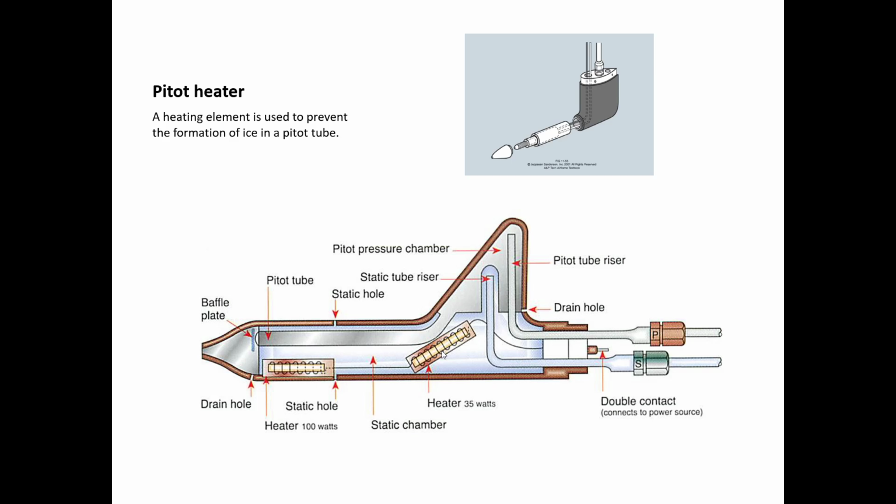Of course, with the heater, you're going to have a power source, and there's a little contact, a double contact, which will connect to the power source. There's safety concerns about grabbing hold of a pitot tube because the pitot heat might be on. And there's been stories of people who really burn their palm quite badly.